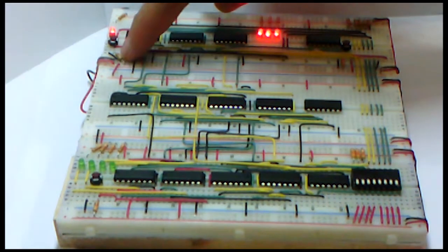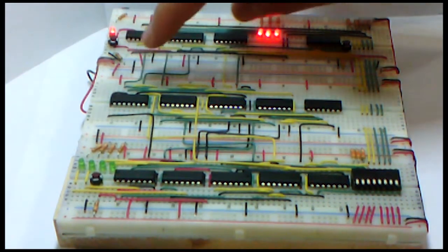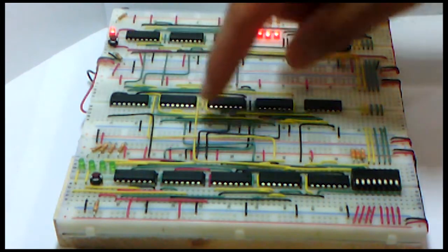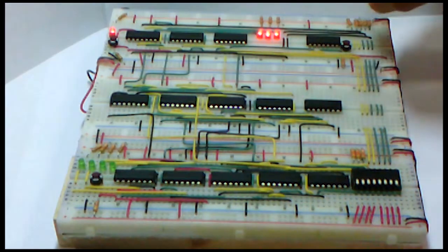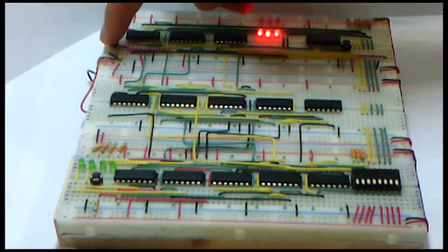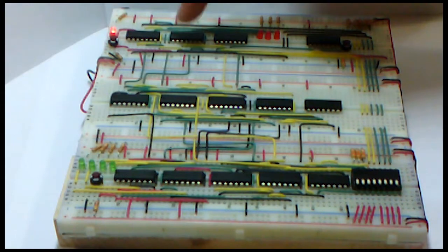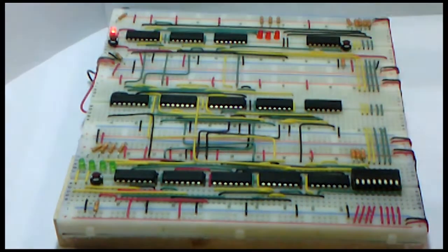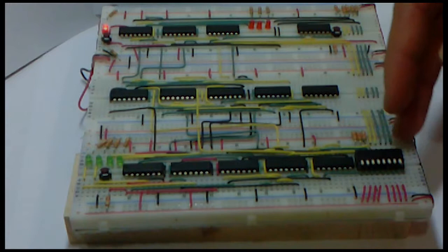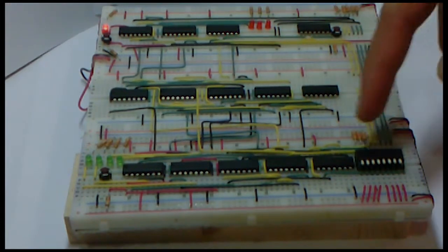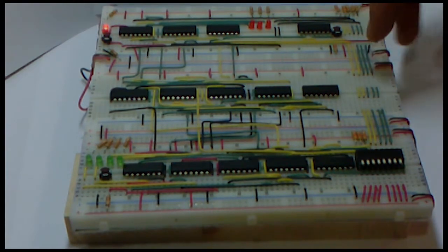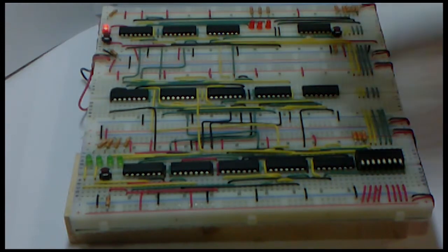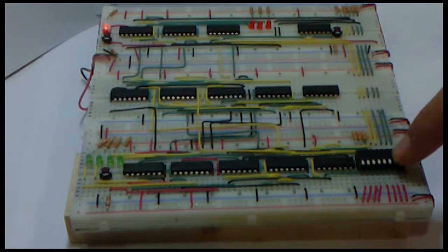The buttons are connected in a voltage divider with the resistors being used as pull-up resistors, meaning that the clear pins will always receive a logic high when the button is not pressed. If the button is pressed, the clear pins will read a logic low, which will override the Qs. All the inputs used in the data buses are connected in a dip switch, which is also connected in a voltage divider with the resistors acting as pull-down resistors. This means that the inputs will always receive a logic low unless the switch has been activated.